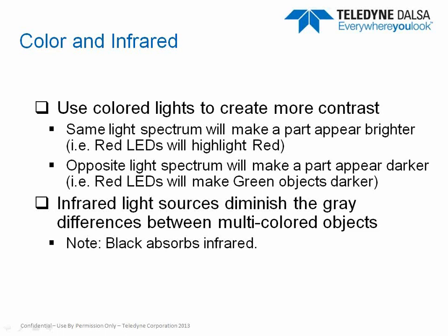A lot of times you have cameras facing each other, and you have lighting. You can use a blue light and a red light, and then filter that from the camera, so they can still fire the lights at each other, but the filter on the lens filters out the other lights, so it's independent. They don't get washed out. Infrared lighting is also good because it flattens out all the colors into just gray, and black does absorb infrared.